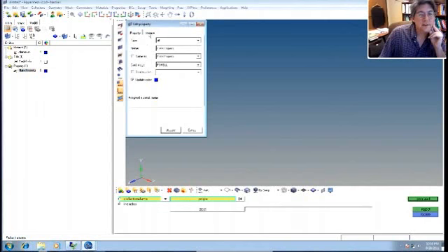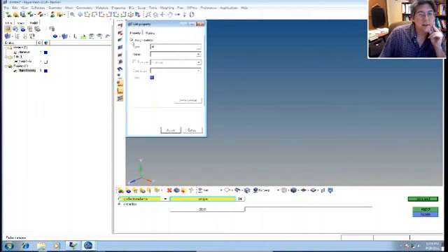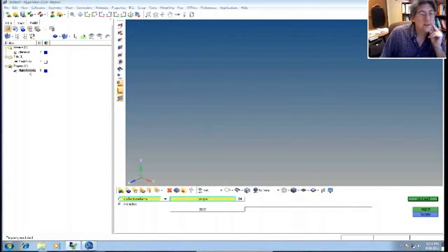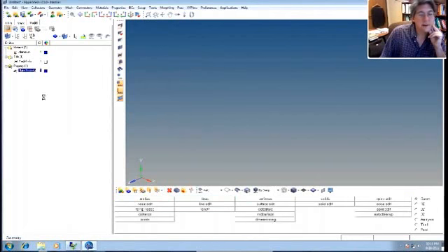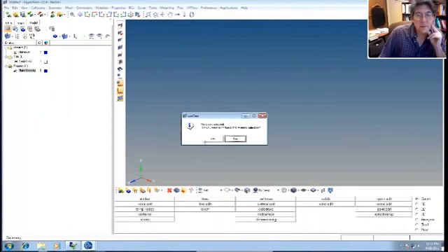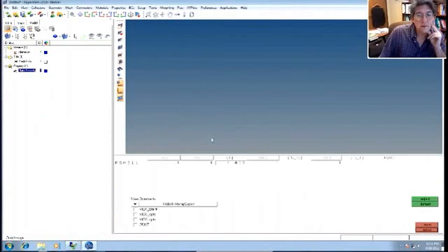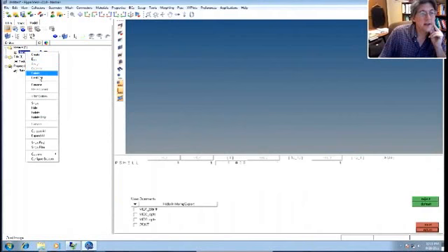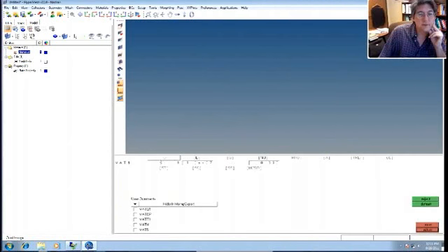And here you can see there's a material tab. I can actually assign the material to it. And I'm going to pick the aluminum one. That's the aluminum one we created, you see? So now we update it. And now if I go back to plate property, do the card edit, whoops. You can see it has the material set to it, material ID 1. That's the material we had. That's the material ID for that guy.